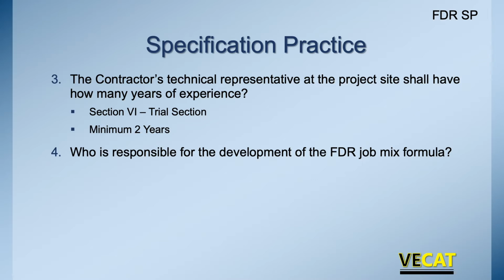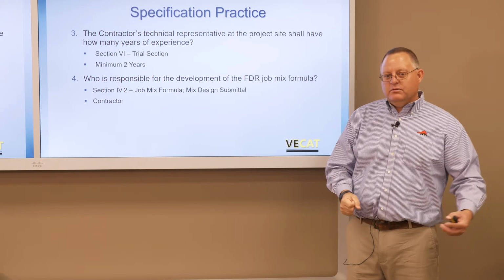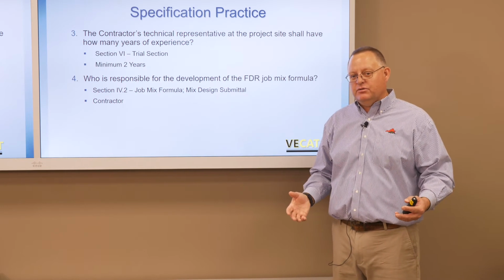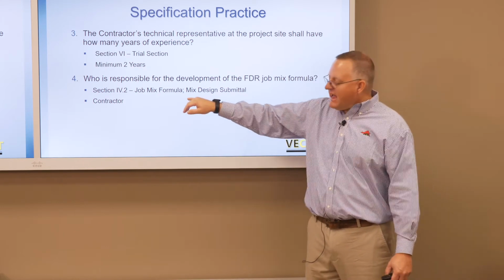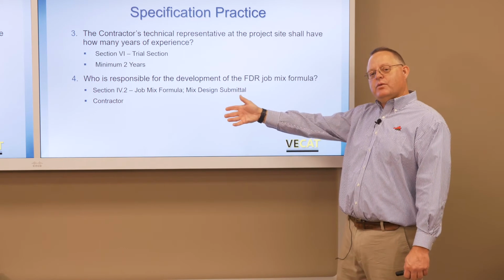Who's responsible for the development of the FDR job mix formula? If we look in the special provision, we go to section 4.2, mix design submittal, and it says the contractor is responsible. Again, in the special provision, it reads this way. If you look through your contract document and there's a special provision copied note that provides the mix design to the contractor, then again, that overrides it.